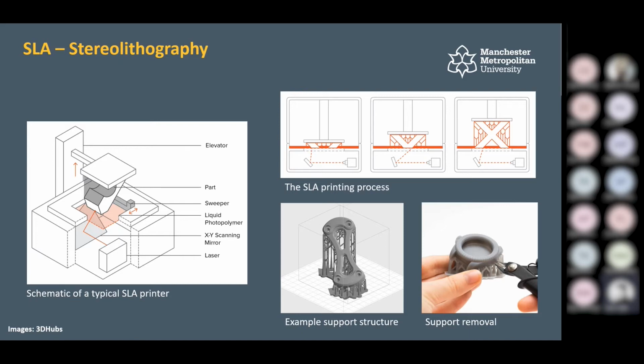So rather than extruding plastic, what this does is it still slices your 3D file, but it's got a little screen underneath, and it's going to shine a light in the shape of your layer. That light then cures a layer of resin, and then the build plate steps upwards a bit, brings it out. It shines the next layer from your 3D model, and that cures to the first one. Build steps up again, cures the next layer, and so on and so forth. And again, you can see this process happening in the top right.